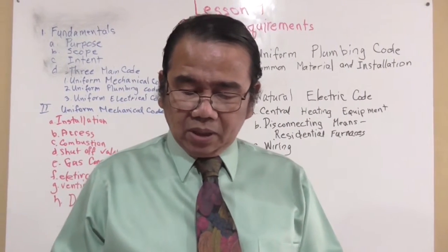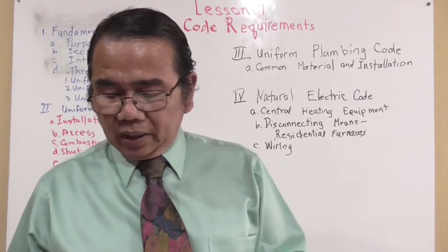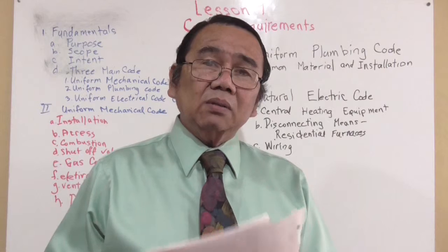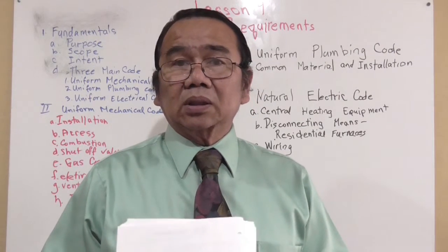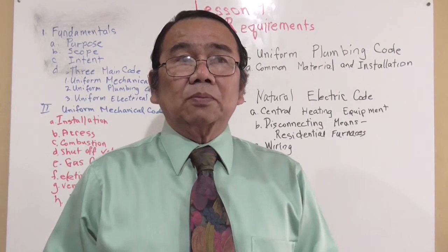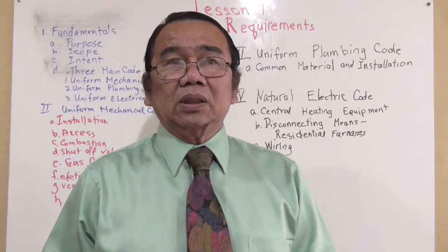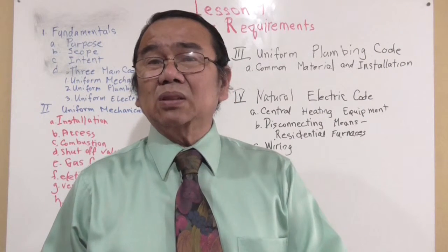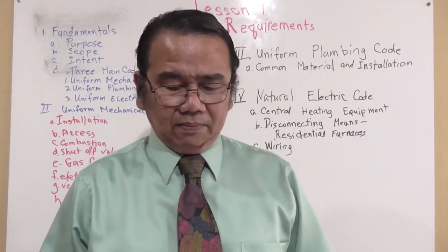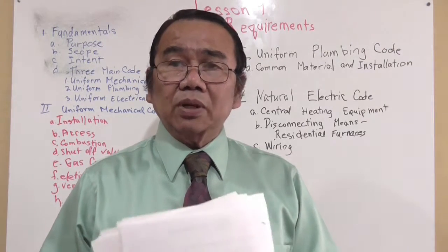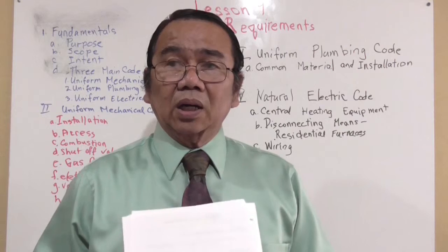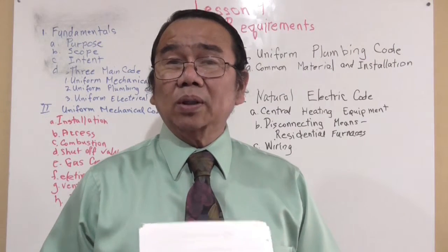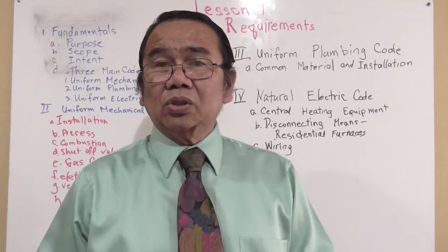All gas piping shall be adequately supported. Okay. Make sure you follow the code in supporting the pipe, because once the inspector comes in and sees that the pipe is not secure, then you're going to get hit on that. Make sure you study and memorize the supporting information and bracing of the parts, because we don't want vibration to distort the piping.